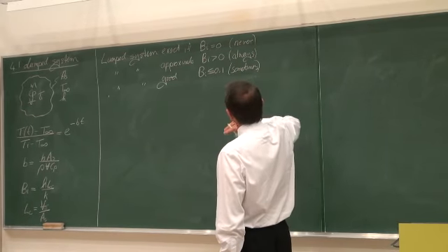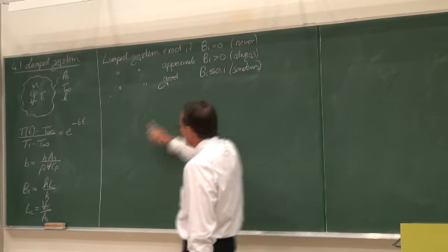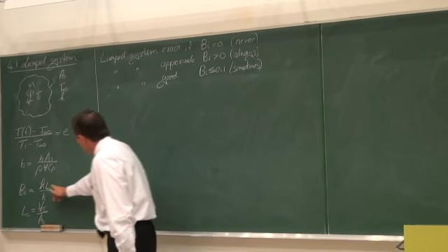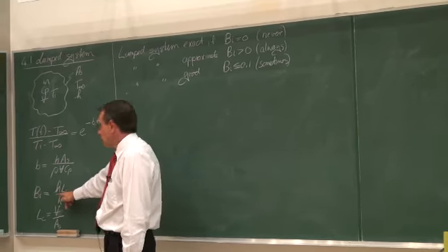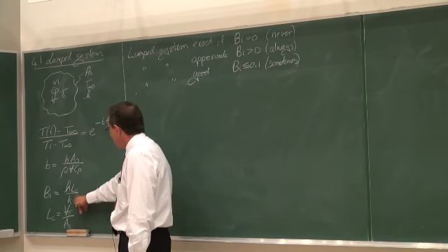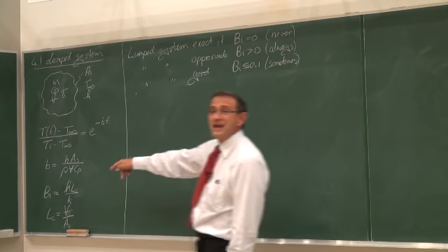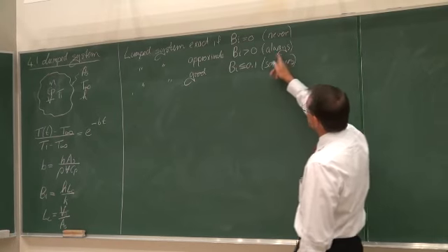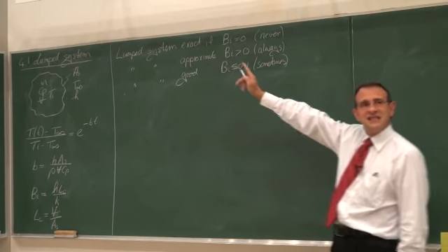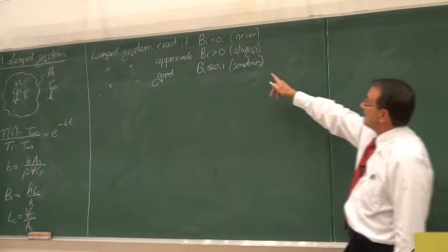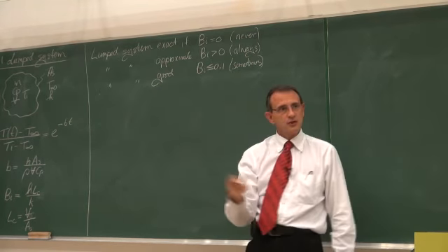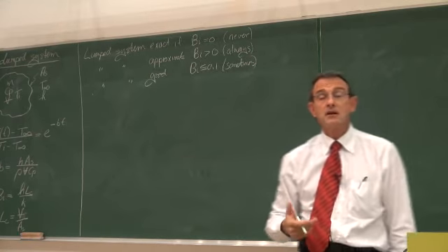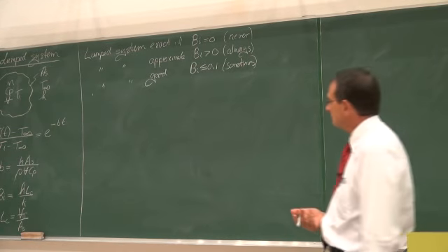If we look at the Biot number, there will always be a value for the heat transfer coefficient, L and k, and not one of the three can be negative. So the Biot number will always be larger than 0, which means that we can always use this approach to give us an approximate solution. Not an exact solution, but an approximate solution.